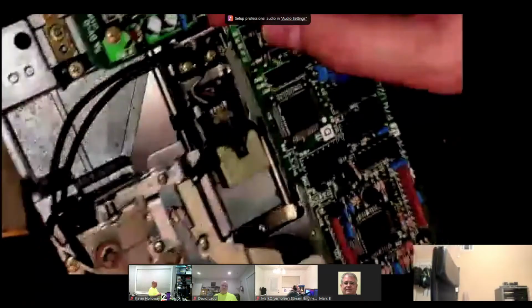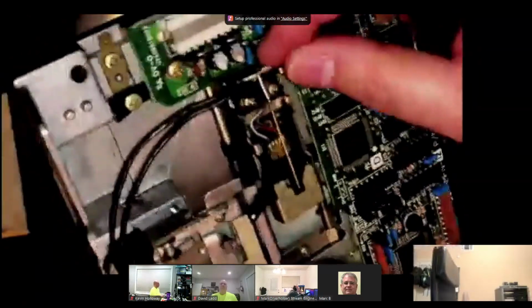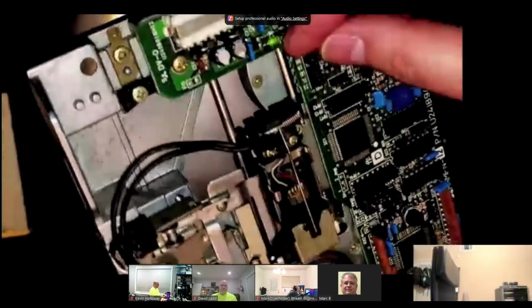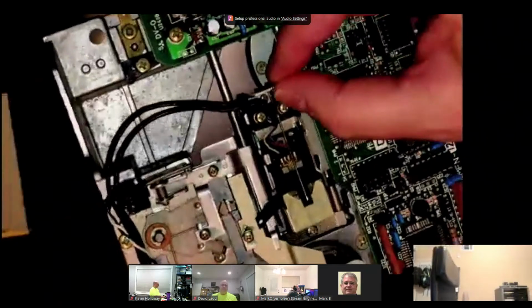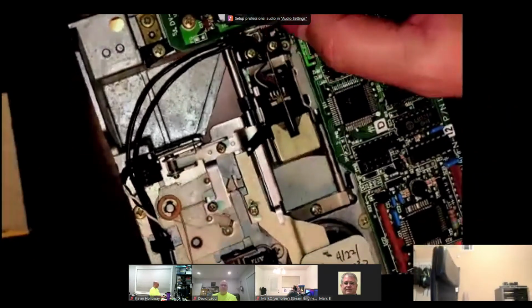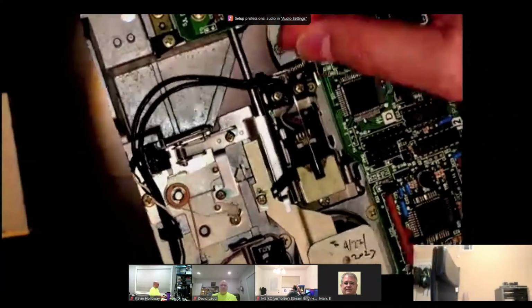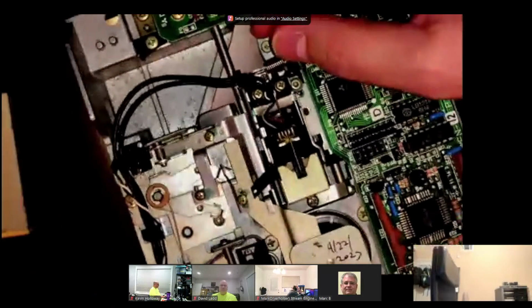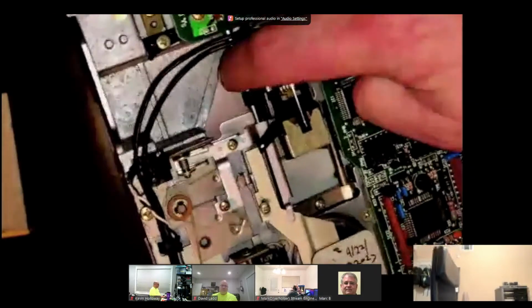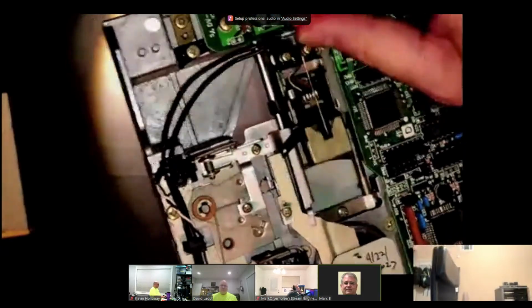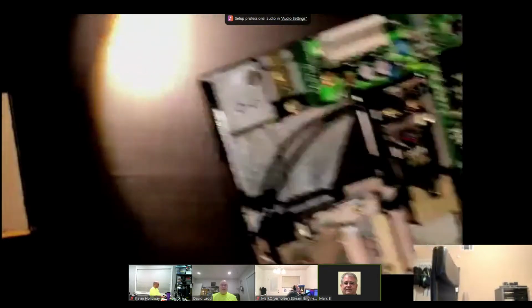and you may want to lubricate this particular drive. They're on these rails, so you use something like a light machine oil. You wouldn't use grease on this. A light machine oil of some kind would be the right kind of lubricant for these rails. Like a sewing machine oil? Yes, sewing machine oil is what I was going to say. Right.